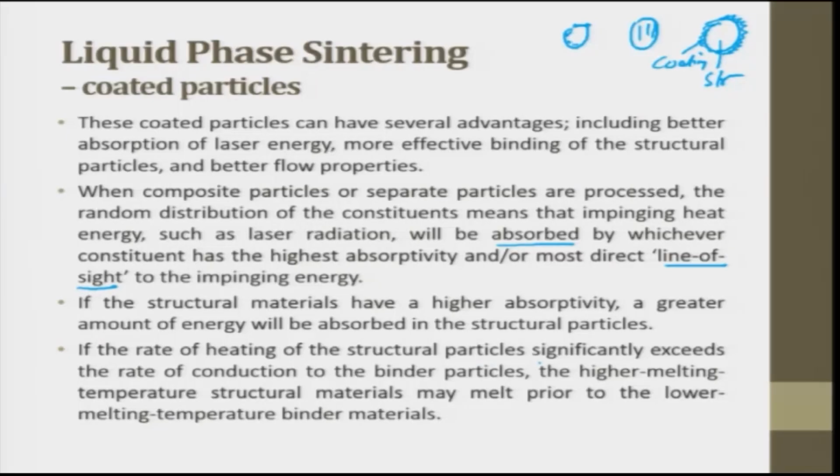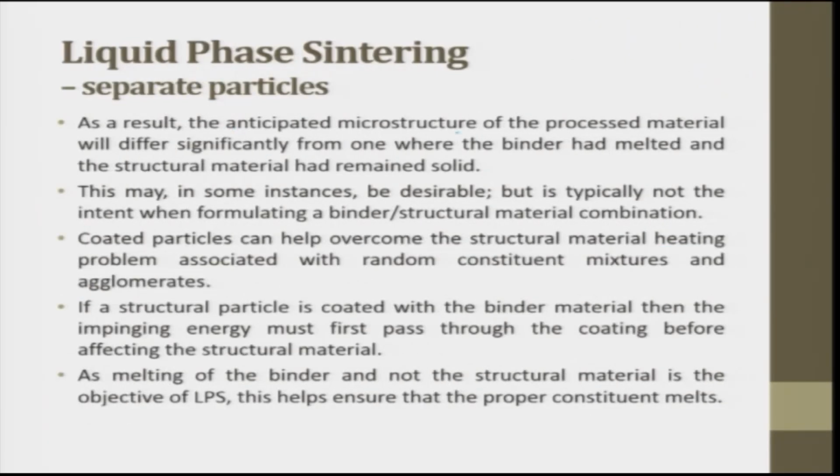If the rate of heating of the structural particle significantly exceeds the rate of conduction to the binding particle, the higher melting temperature structural material may melt prior to the lower melting temperature binder. This seldom happens, but if you are smart for your application and want to tweak, you can do this also. As a result, the anticipated microstructure of the processed material will differ significantly from one where the binder had melted and the structural material had remained solid. Completely different phenomena can happen. This may in some instances be desirable, but it is typically not the intent when formulating a binder and structural material combination.